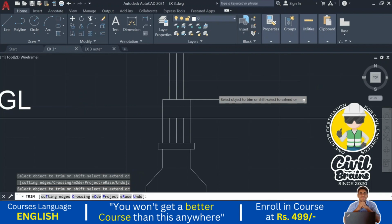So here we are considering the frame structure, RCC frame structure. So what all things are included in the RCC main structure? In the RCC frame structure, there is a footing below the ground. After the footing, there is a plinth beam at the plinth level or at the ground level, depending upon the structural stability. We are going to give that one plinth beam. Above the plinth beam, there is a lintel, and above the lintel, there is a RCC beam, or we can say floor beams, and above that there is a RCC slab. Okay, so these all components are included in this frame structure. Okay, so we need to show everything.